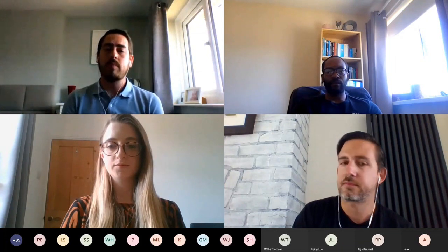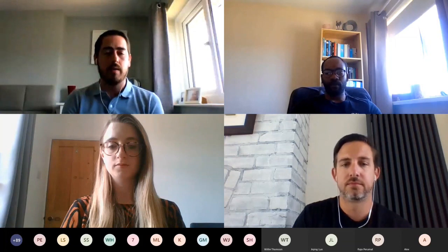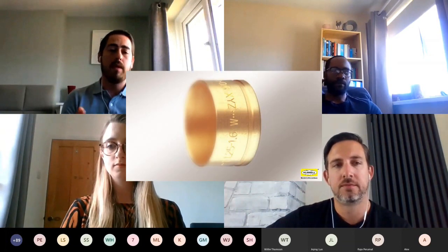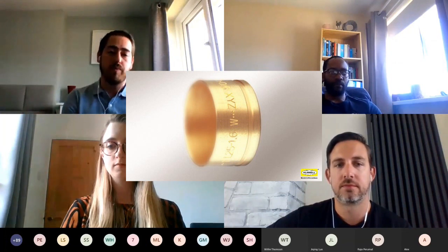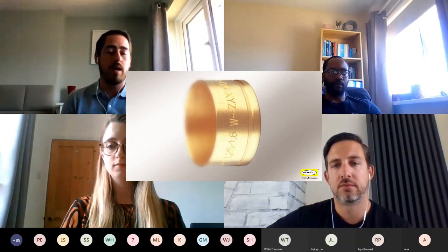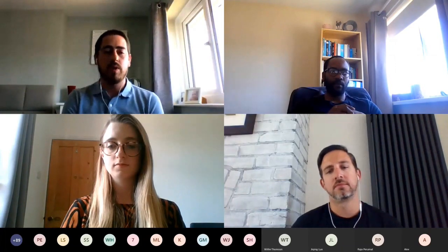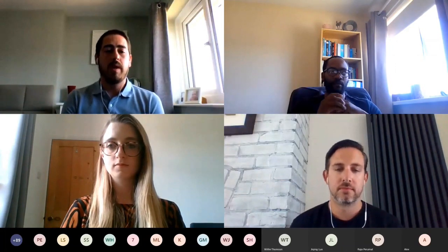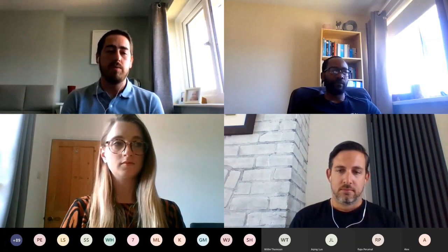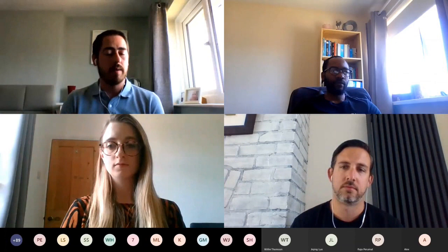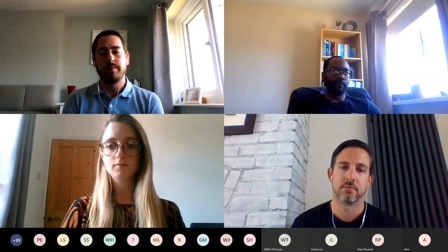You do have other parts of the cable gland, such as an internal clamping ring that gives you grounding. These are used for armoured and braided cables. Our reversible armour clamp allows you to clamp onto braid, steel wire armour and tape. And we also have in our 7 series range, which is predominantly used in the US, the Diablo, which is a compressible copper cage, all inspectable. You're able to dismantle the cable gland and inspect all of these components as well.